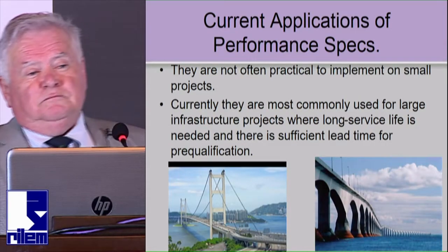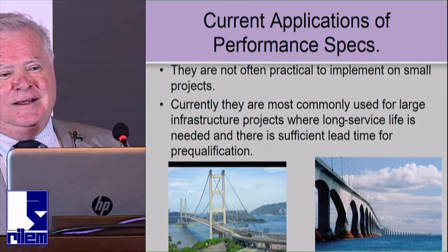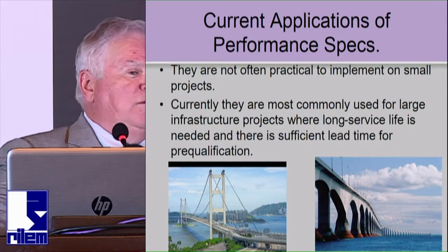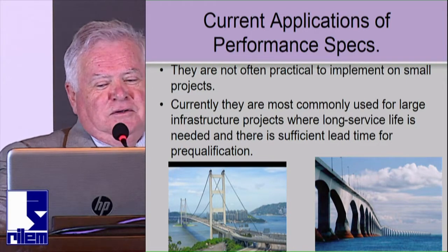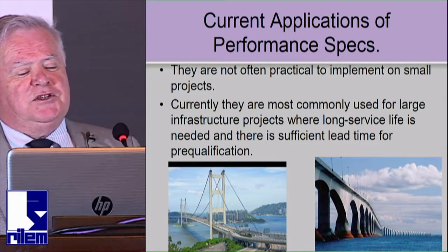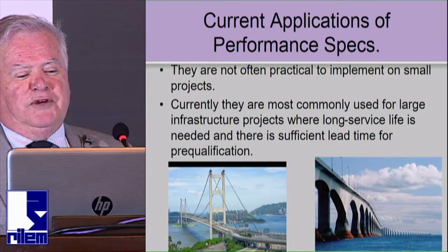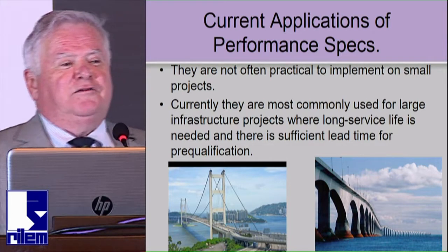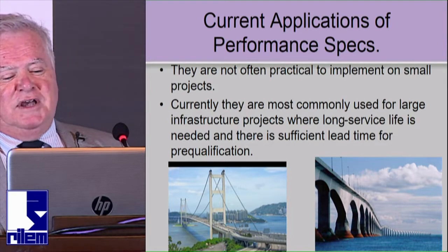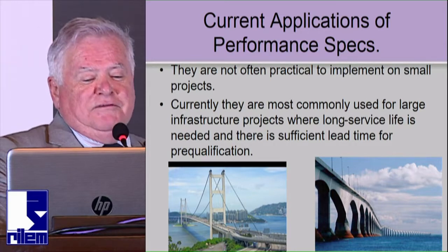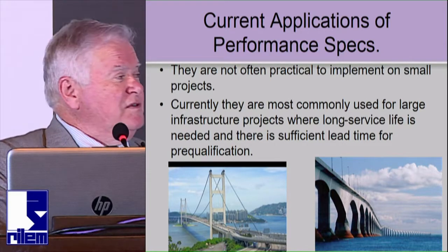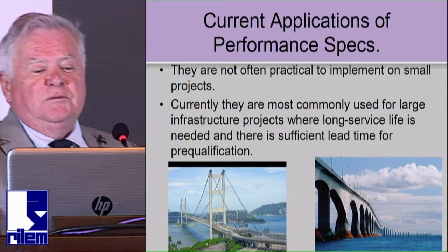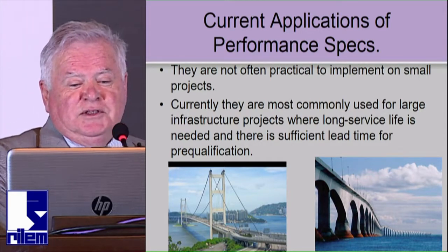Now, this is not for all concrete. Obviously, if you're doing residential construction or a lot of commercial construction, you can't use this currently the way it is because you don't have enough lead time to do a lot of the pre-qualification testing that's required. This is practical for large structures that have lead times and where you need long service life. And we've seen several of these projects where people are specifying long service life and using performance-related specifications to get what they want.